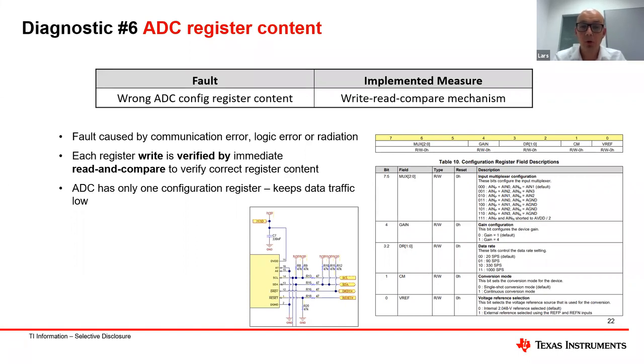And if you have a more complex A-to-D converter, you may read entire register banks within a diagnostic test interval all the time. This could be quite busy on the SPI or on the I2C line. But for us here, we definitely change the configuration of the register quite a bit, and we can also always be assured that it works by reading back the register.